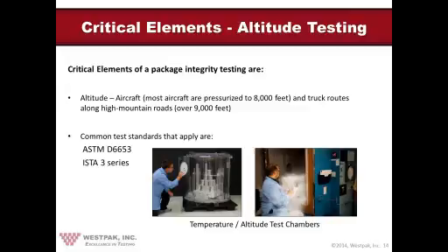Now, there are some variations to that. Some of the newer aircraft, I think the Boeing 787 Dreamliner, they call it, is pressurized to 4,000 feet because it keeps more moisture in the atmosphere, and it doesn't dry out nearly as much. Those of you who have flown in that plane know that there is a difference. Another question was, okay, so if 8,000 feet is the limit that you're expected to get exposed to, how come you test at 14,000 feet? Isn't that an overtest? And the answer is no.